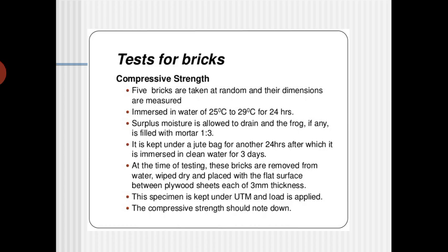That is why, before immersing the bricks, your job is to make sure of the initial temperature as well as the final temperature. Then surplus moisture is allowed to drain after 24 hours.